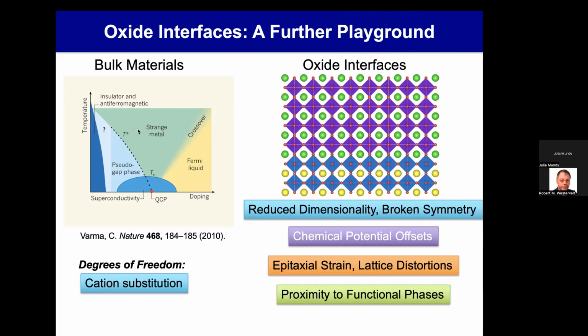So this is also very powerful, to be able to think about breaking up some cool property that you want into components and then trying to search for that property at the interface. And then also, I'll show you at the end, a big part of what I actually work on is these metastable phases. So actually making materials that are not the thermodynamic lowest ground state energy of the material, but whereby we can template these materials using this approach. So making a material that wants to be cubic, we can make it hexagonal by just putting it on the right template. So we can fundamentally change how the atoms want to arrange in this thing.